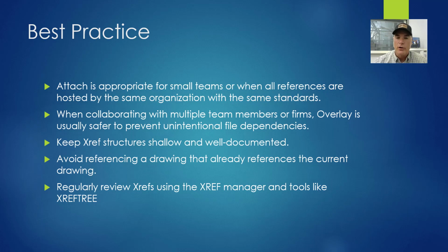But if you're working with multiple team members or multiple firms, overlay is usually the safer practice to prevent unintentional file discrepancies. The other thing you'll want to do is keep your XREF structures shallow and well documented. Try not to have things on several different levels, and avoid referencing a drawing that already has references to that current drawing. That creates that circular reference.